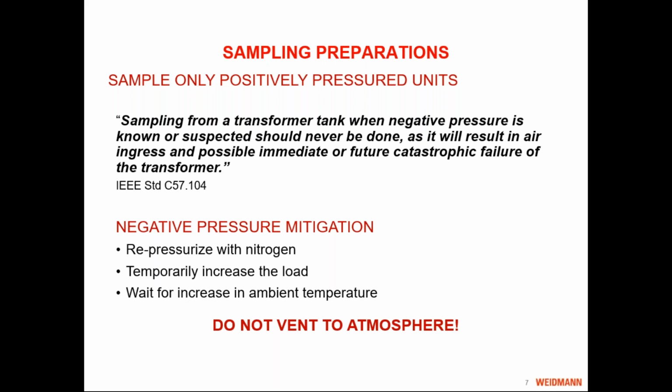One thing that some people will try to do is not recommended: if you're under vacuum, don't open a valve and crack it to atmosphere, for the same reasons I talked about earlier. If you do that, you're going to pull outside air in, and not only will you get air bubbles, but you could potentially be pulling in moisture and other contaminants that might be floating around in the air inside your transformer, and you definitely don't want to do that.